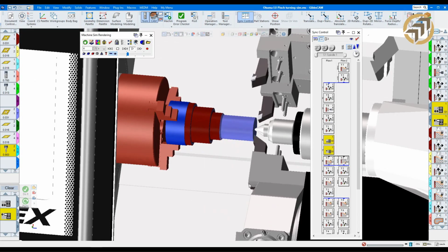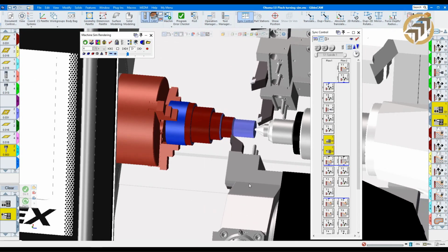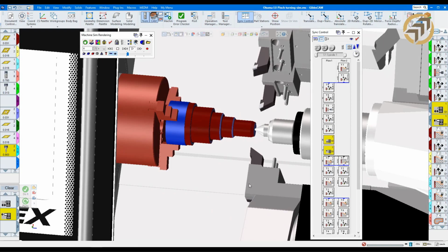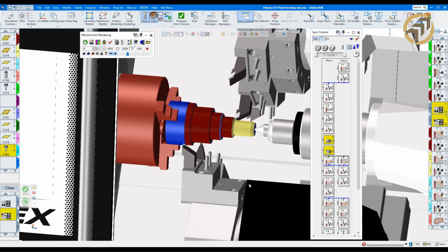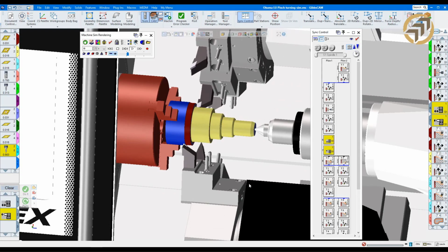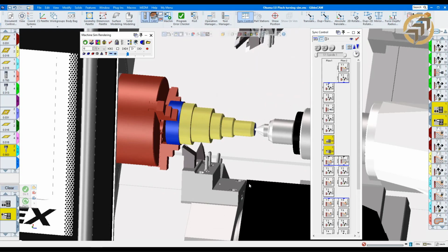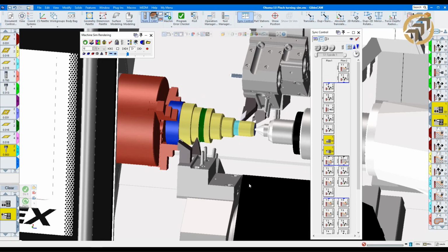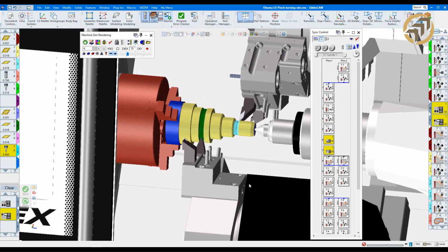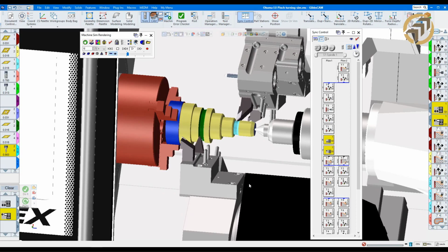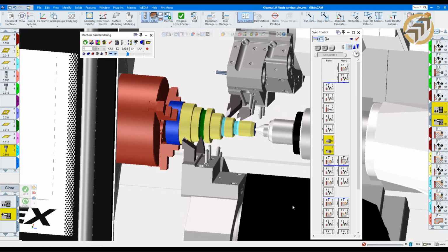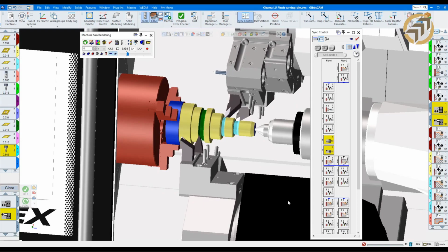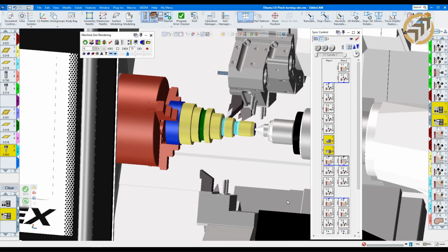So of course, you can see now different colors. You can set the system to give us different colors either per tool or per operation. So you see this one, the lighter color. Now the lower turret is waiting until it can go, and it tells the upper turret to work together. And these waiting for each other we also call sync modes or wait codes.